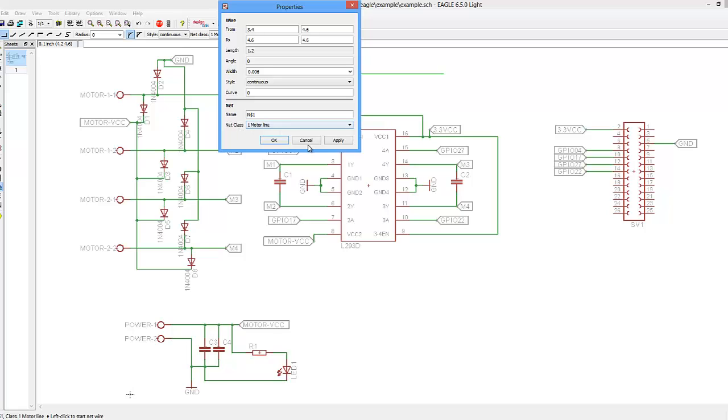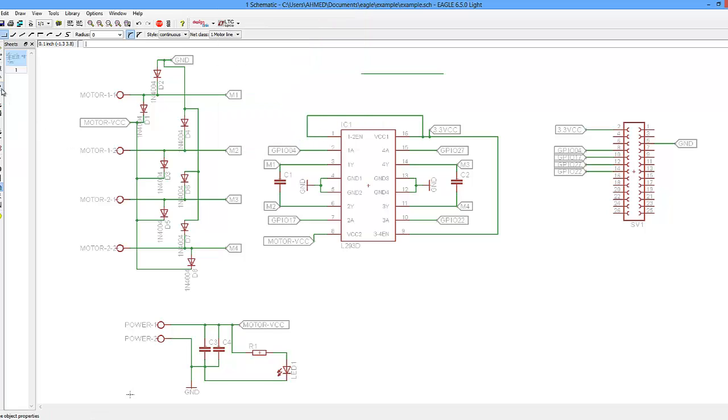So you pick which one you want to be default while you are routing. So I make the default one the 1 mm, which is carrying data lines, data information. So there is not a lot of current passing through it. And then the VCC and the motor lines I just modify by myself, straightforward.